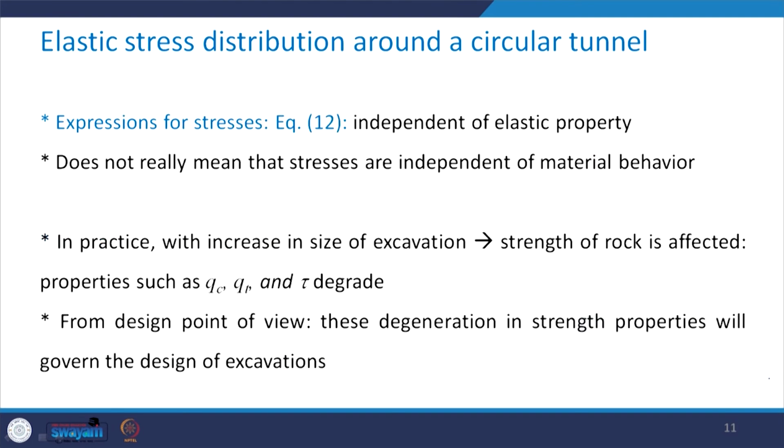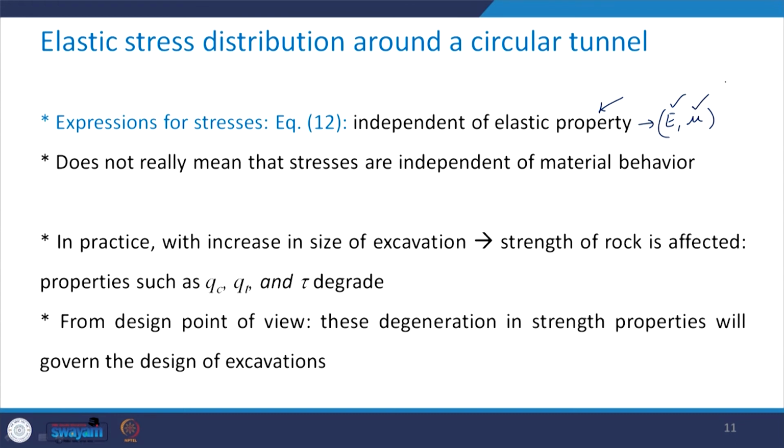Now, the expressions which were given for these stresses using equation number 12, we have seen that these are independent of the elastic properties. What were those? Like E and nu. So, those expressions for sigma r, sigma theta and tau r theta, they were not a function of these E and nu. So, this does not really mean that stresses are independent of the material behavior.